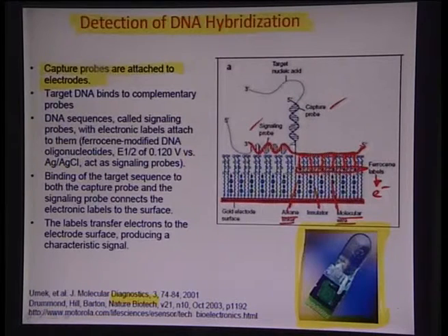All right. So, you have a capture probe here bonded to one of these alkane linkers, which is an insulator, and you have a signaling probe here which has a ferrocene group and which is lying somewhere around on the surface. So, this is the situation. Now, let us suppose we have a target nucleic acid which we want to detect, okay, and very intelligently the system can pick this up by aligning the signaling probe flat to the bed of the molecular nanowires and getting the ferrocene very close to the molecular nanowires.